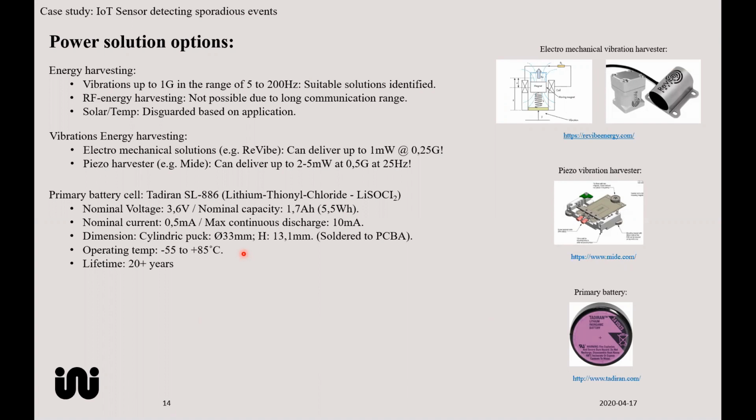that. If you now look at the power numbers that we calculated and I shared with you regarding narrowband IoT and Bluetooth Low Energy, the conclusion was that narrowband IoT could last for approximately 2 years. But this is purely based on the capacity of the battery and the energy consumed by the system if we would have used narrowband IoT. The conclusion that I mentioned, that the power delivery capacity was less in cold temperature, makes narrowband IoT less useful, and 2 years is questionable.